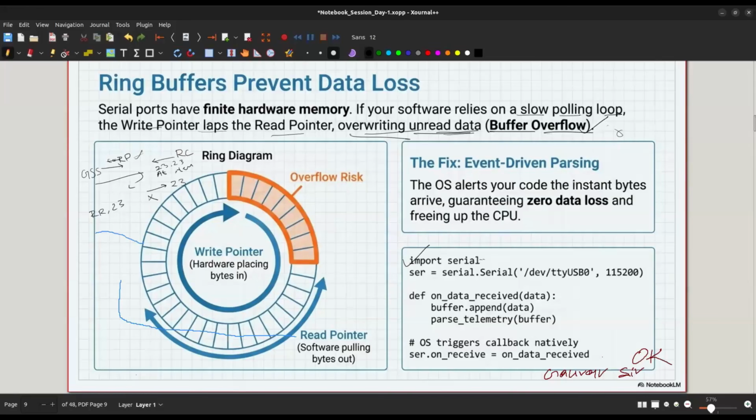What we are trying to do here is handle the serial data. The serial library has a function named serial.Serial. You can just pass in your port like COM3. In Windows, you use COM3. And then you pass the baud rate like 9600, whatever baud rate is already coded on your microcontroller. So you pass in a variable like data, which is equal to, using the serial library, you are asking the serial function to read the data coming from this USB port